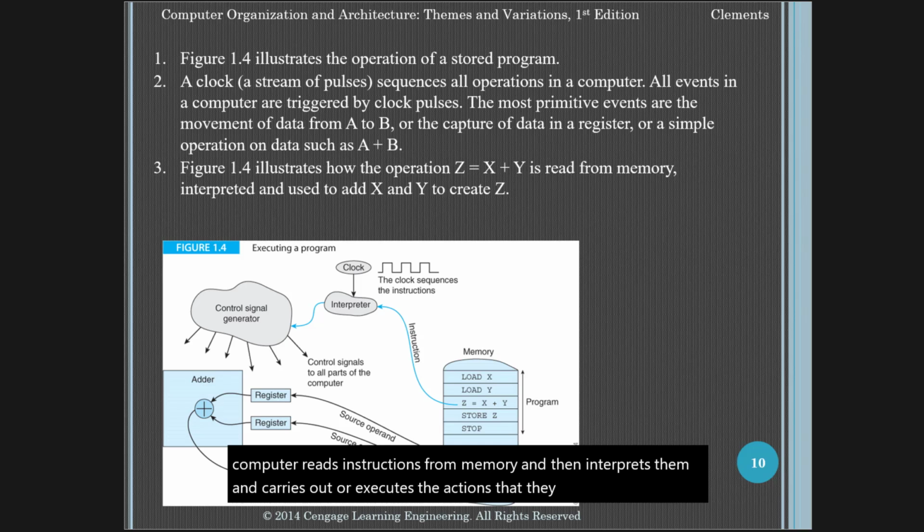When an instruction is executed, it may be read as data from memory, or we may operate on data, or we may store data back into memory. And I mentioned those registers. The registers are those internal single element locations that hold data, and they're tied to that system clock. Now, that system clock is what we're talking about when we talk about the speed in megahertz of a processor.